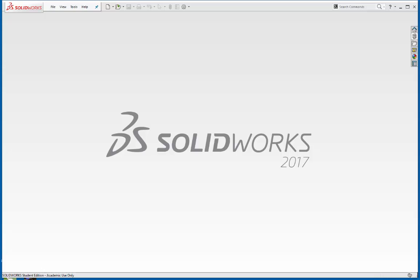This is Dan Abbott. This video will cover weldments in SolidWorks with an overview of the process of creating weldments and some suggestions for avoiding problems or potential problems down the road. The weldment process requires that you take a profile and sweep it along a path like a swept solid.